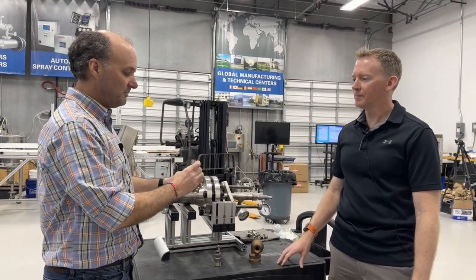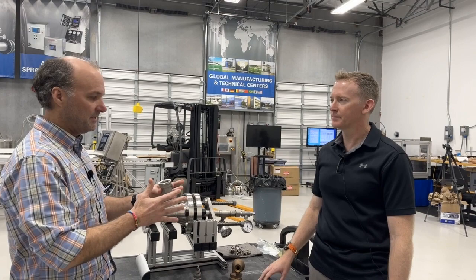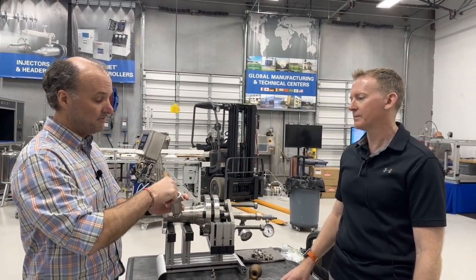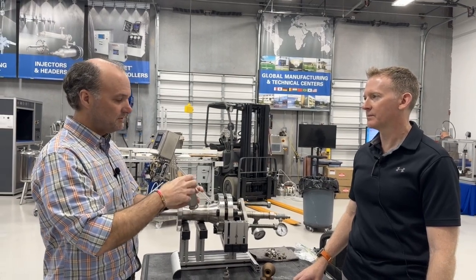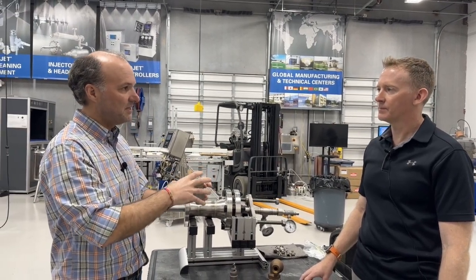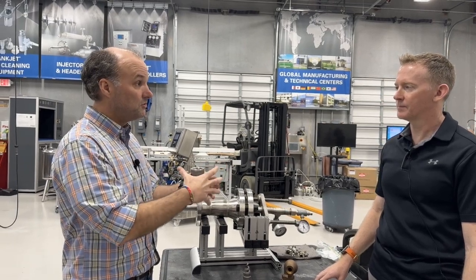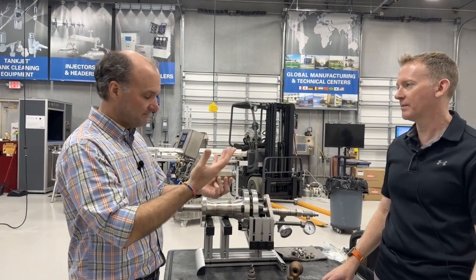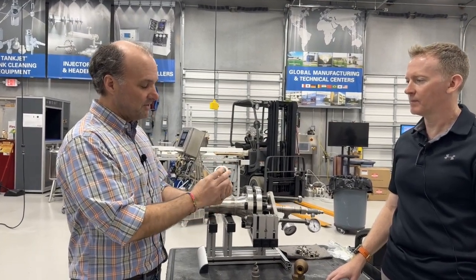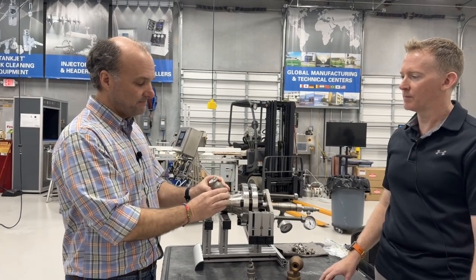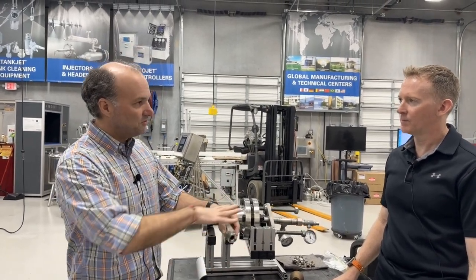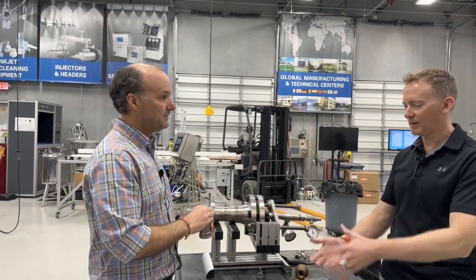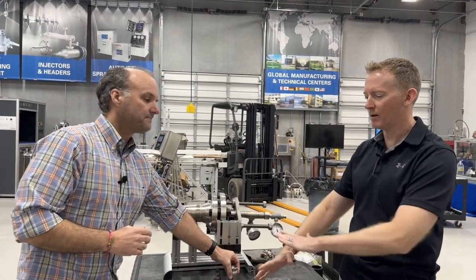And you mentioned pluggage, and pluggage can come from different ways. It can come from solid particles that can't flow through by themselves, and it can come from buildup inside. So maybe you have some mineral deposits that build up over time, and that can help to reduce the amount of free passage. And also pluggage can come from the outside. Sure, I've seen that before. Exactly. So anyway, the full cone nozzle, the limiting factor is here on the inside, and it will give you a full cone spray pattern. So it's a very round full cone. If you can imagine like a splatter picture, it would be 100% dots on the target.